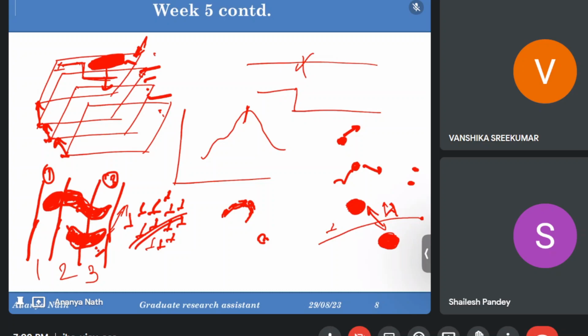But for edge dislocations, their movement and the Burgers vector are perpendicular. So they need to find another slip plane which has the same direction as their dislocation movement, and only then can they cross slip. So it's just leaping from one plane to another plane. But for edge dislocations, it's like climbing, jumping from one plane to another plane because they cannot cross slip. They do not have the preferable Burgers vector direction and slip direction. So for edge dislocation, this is called climbing. For screw dislocation, this is called cross slip.